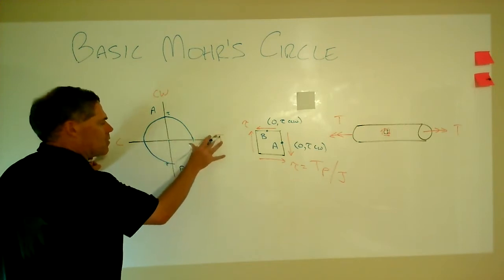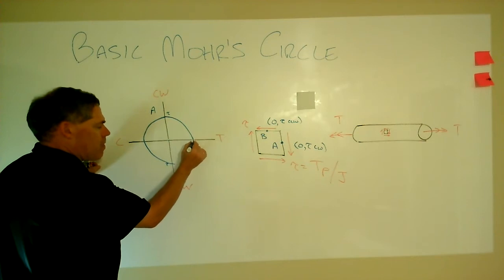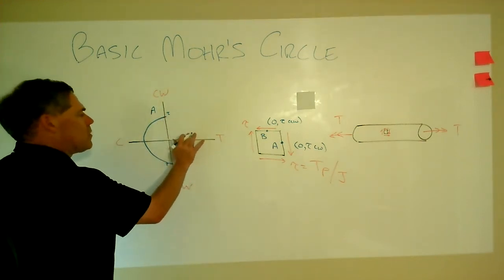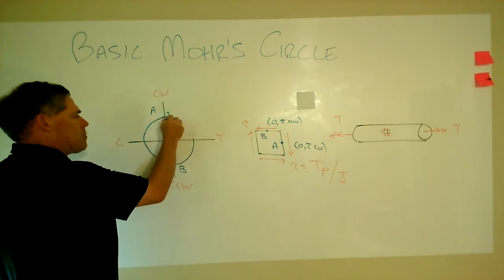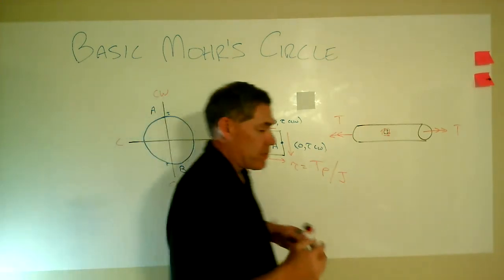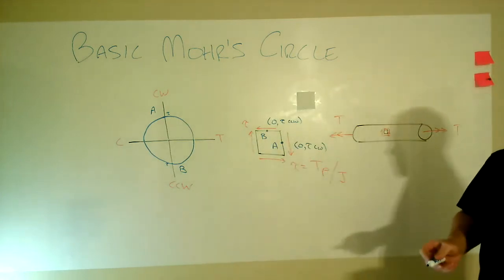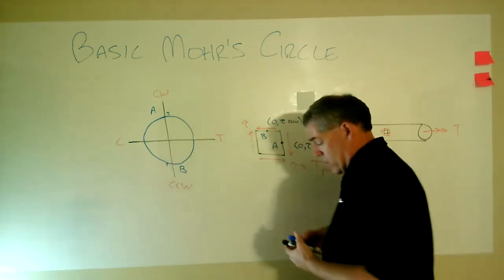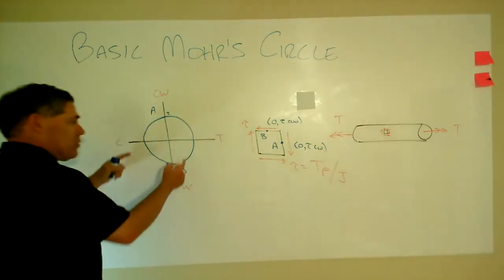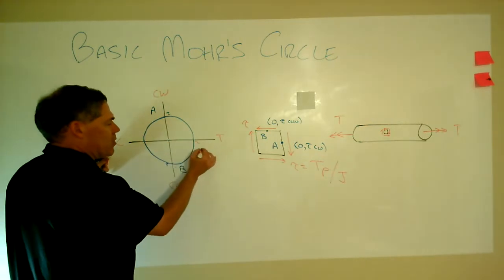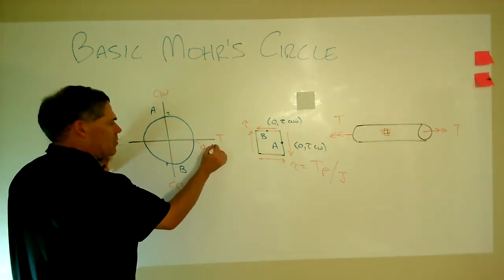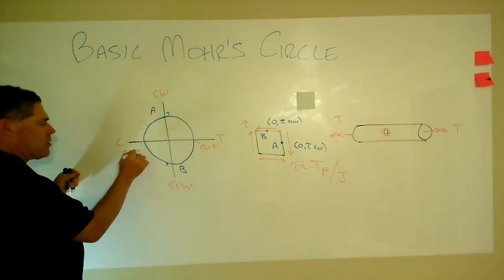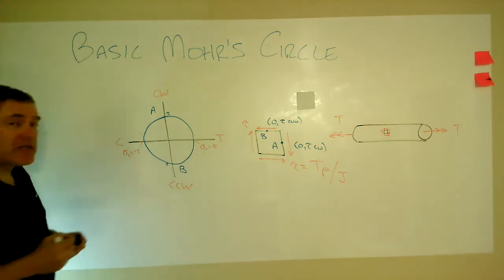I don't like that one very well either. So while you're catching up to me, I'm going to slightly improve it. So that's the basic Mohr's circle for this situation. Note, it is centered right here. Note that the maximum normal stresses, otherwise known as the principal stresses, will also be equal to tau, and on the other side, also equal to tau. One's in compression, one's in tension.